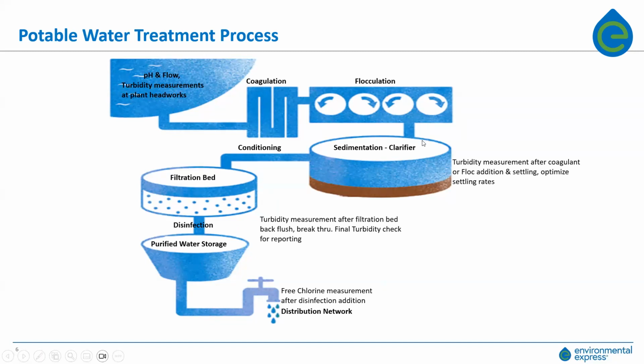That dissolves, and as that flow enters the clarifier, the flocs or colloids begin to form at the surface. As they get larger and heavier, they begin to settle out and slowly float to the bottom of the clarifier. Now, these clarifiers are normally cone-shaped in design and will have a valve and a pump at the base so that they can remove the sludge once it hits a certain level in the tank.